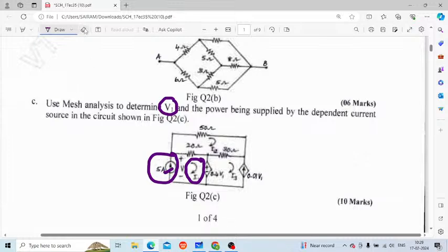Now look, here also there is V1, right? Here also V1 is there, and here also V1 is there, but this is a voltage-dependent voltage source, students. There is a voltage-dependent voltage source between the two meshes, and here this is current dependent, once again, the current source, sorry, current dependent voltage source, CDVS. This is mesh 3, and the mesh 3 current is I3. So now my I3 becomes equal to 0.01 V1, right?